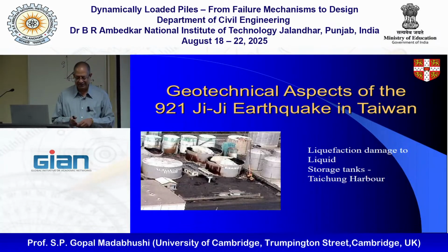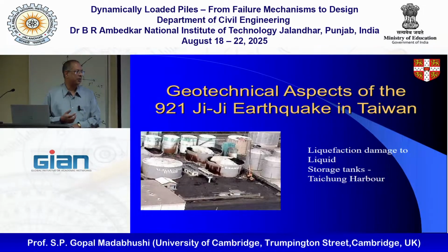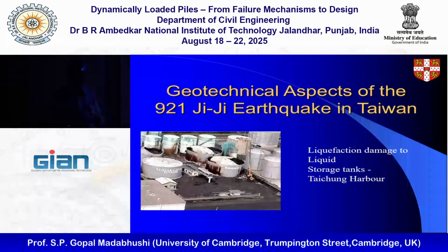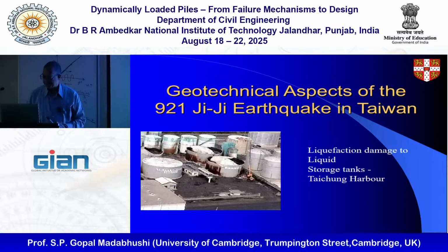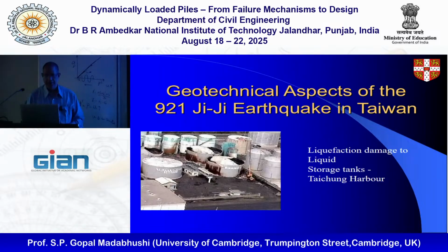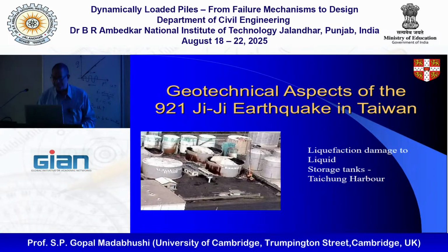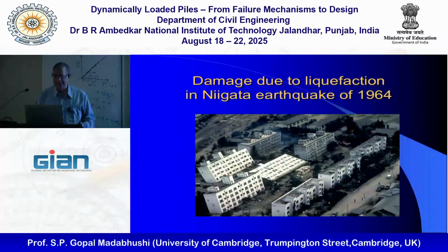Why? This is a very interesting structures problem, because I have a cylinder with fluid, and when I shake it, the cylinder wants to go oval and come back, right? But I have a shell sitting on the top, and the only way it can accommodate this is if the shell pops out. And so people look at this fluid structure interaction as well. Again, I've shown you this many times, we don't need to spend time on these kinds of problems.